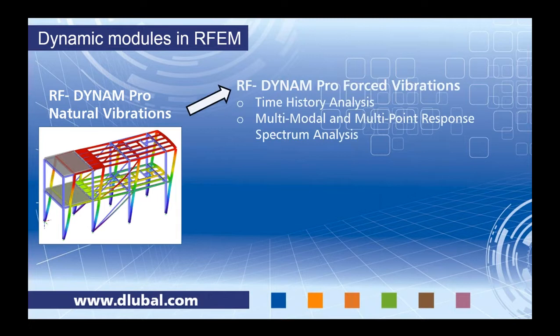Then we have our RF-DYNAM Pro Forced Vibrations. This is for a time history analysis, and it's for a multimodal, multi-point response spectrum analysis. So essentially you can perform a response spectrum analysis differently throughout a single structure. We won't be using this module today.